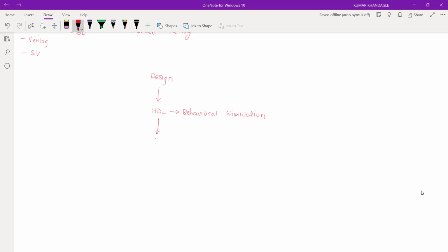Then the third step is to perform synthesis. This will basically transform your HDL to the FPGA primitives that are available for the specific device family which you have chosen while creating a project. Here also you could adopt certain optimization if you have specific constraints.